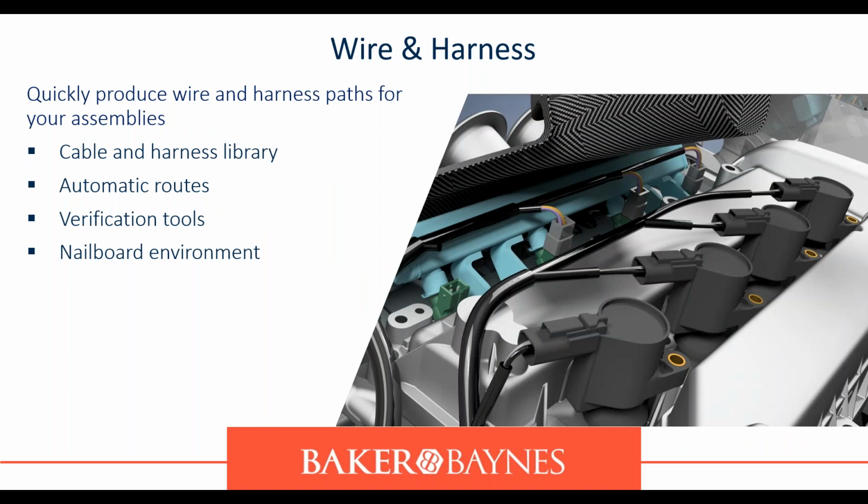Wire and harness. Quickly produce wire and harness paths for your assemblies. Automatic routing capabilities save the time it takes to draw spline data. In the image that you see there, all of that was designed in Inventor. Everything that you see that you can do in Inventor, everything is included. If you buy Inventor, everything will be there for you to be able to design exactly what you see there. You verify minimum bend radii on wires, and automatically generate nailboard drawings from the 3D model.